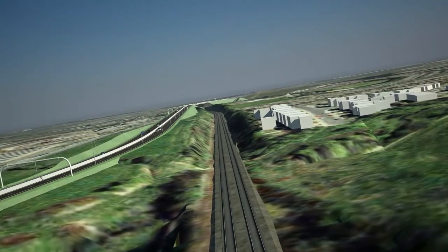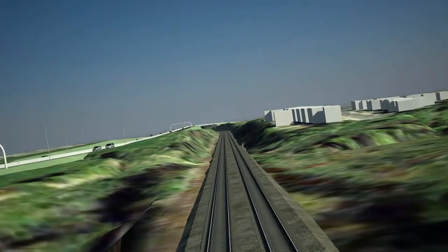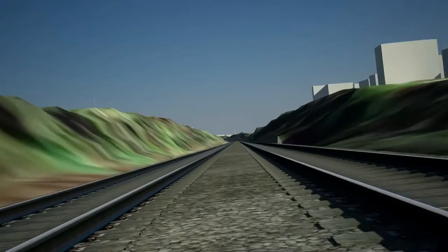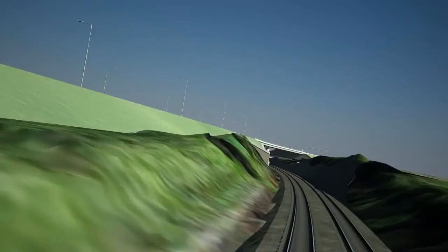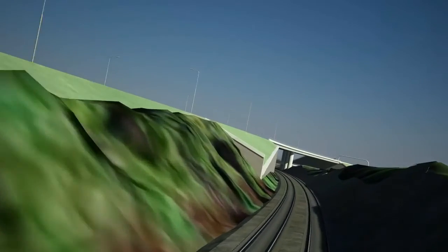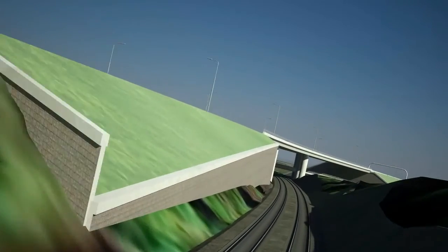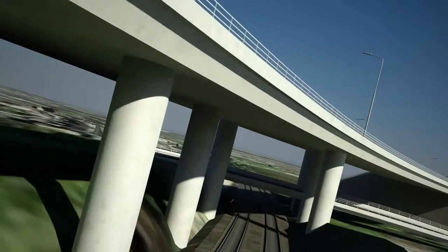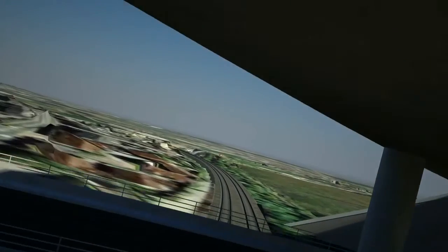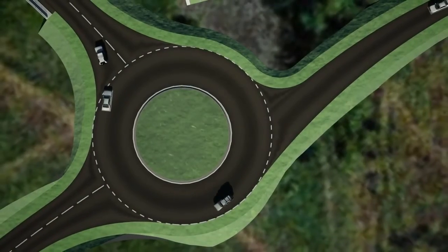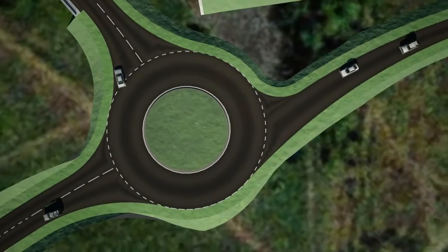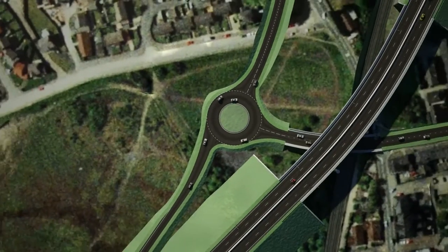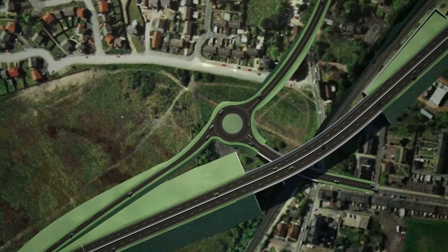So for example, if we have a look at the series of camera animations that I have here, I'm really picking and choosing where I want this camera to look, what the movement of the camera is, and also how fluid I want this camera to be. So this is really the strength of 3ds Max Design. It's a cinematography tool that allows you to place cameras and animate them everywhere and anywhere you want. So really use your imagination and creativity to drive attention to your project exactly where you want the attention to be. So we're going to have a look at how we can create camera animation outside of those corridor feature lines.